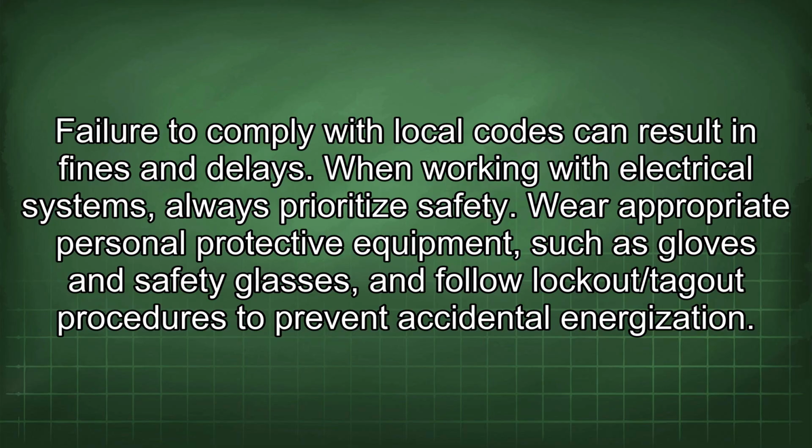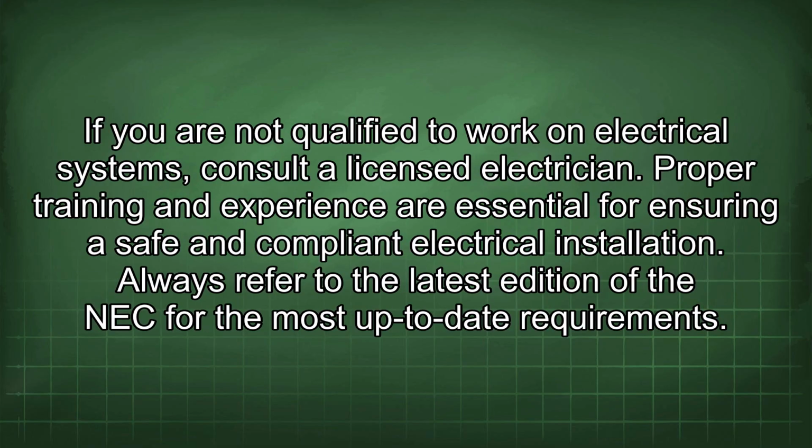When working with electrical systems, always prioritize safety. Wear appropriate personal protective equipment such as gloves and safety glasses, and follow lockout/tagout procedures to prevent accidental energization. If you are not qualified to work on electrical systems, consult a licensed electrician. Proper training and experience are essential for ensuring a safe and compliant electrical installation.